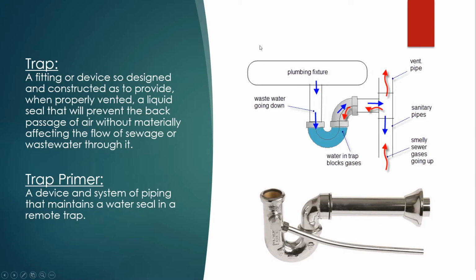So with the P-trap, anytime you use water here, it'll flow and it'll keep it fresh. But then you do have, pretty much behind the wall of any P-trap, a vent pipe, and this will either connect to a series of vents and go out of the roof, or somewhere where you won't smell it, so somewhere high.